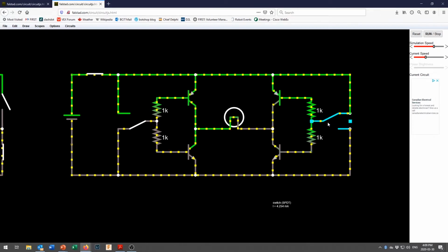Let's see what happens if we turn that switch. And now, in this configuration, we've got electricity coming from right here, passing through right here, turning it clockwise, coming out here and getting back to ground. Very important that it's able to get back to ground and get back to the original power source. And using the PNP and NPN transistors in here also makes it more difficult to short out either side because you're either on or you're off on that side.